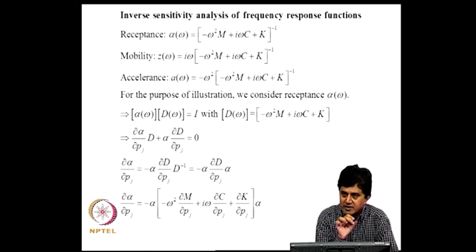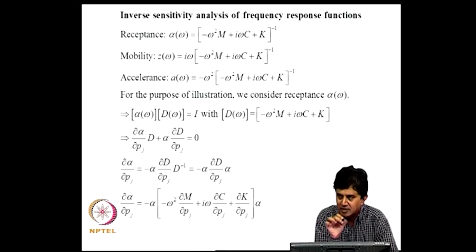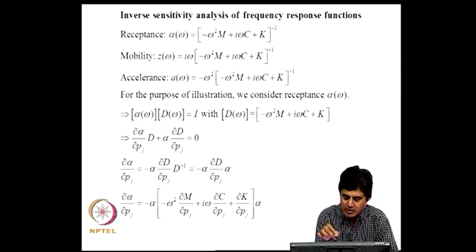From the given frequency response function, a matrix of frequency response functions, we extract the natural frequencies and mode shapes. If you do not want to do that extraction, you want to deal directly with what has been measured. Even that FRF is processed from what we measure, but it is a relatively more primary quantity than the secondary quantities like natural frequencies, mode shapes, damping and so on.